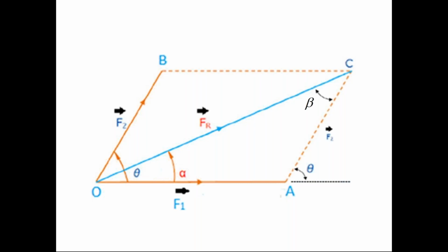We are preparing this parallelogram on the white paper. So since this parallelogram is prepared on the white paper, to find out the resultant force of F1 bar, F2 bar, we call this the graphical method. The parallelogram law of forces is a graphical method.